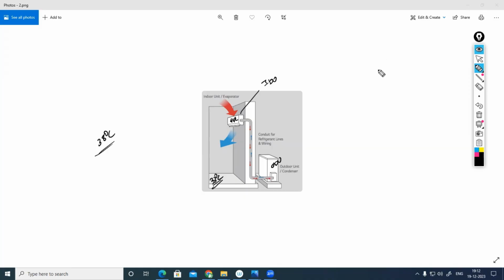Eventually, for 24 degrees Celsius and 50% relative humidity, each kilogram of air should have nearly 9 grams of water, right? That's the humidity ratio as per ASHRAE. Once it has been achieved, the condensation will stop. After that, the room temperature will start to increase. Until the humidity ratio is achieved, we can't witness a big change in the air.